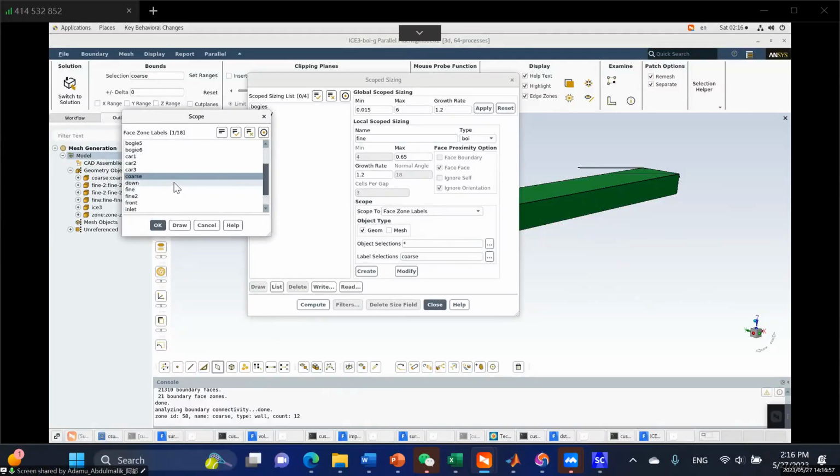Because I want to study the intercarriage gap, I also put a mesh, that's a BOI, to define the mesh around the intercarriage gap to be smaller there, because that's my area of study. I want the mesh there defined so that it can have a good result there. Because the finer your mesh, the better your result. So that's why I use this fine tool in that area.